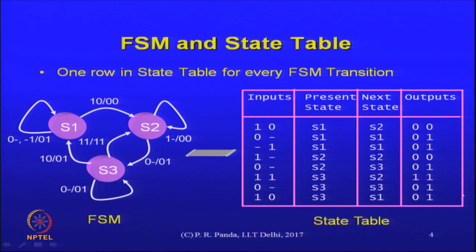first let us understand that there is a diagram that is used for illustrative purposes. Equivalently, one could look at the FSM as just a state table. These two representations on the left and the right are equivalent. So, I have the input part and that is the output part of the state table. We have these columns in the state table that refer to an input section, a present state section, a next state section and an output section.